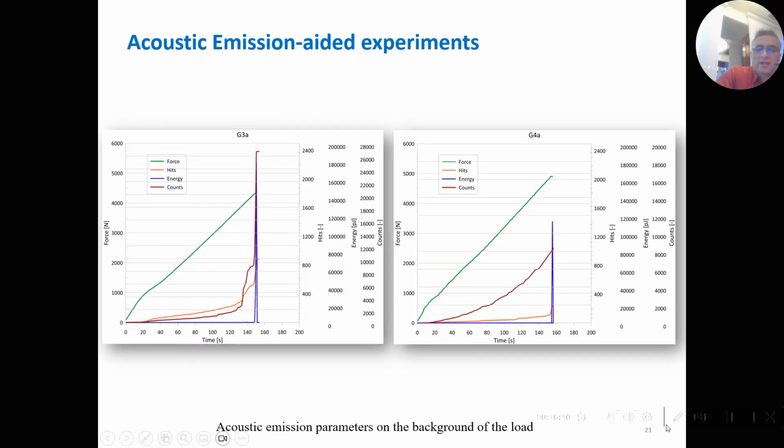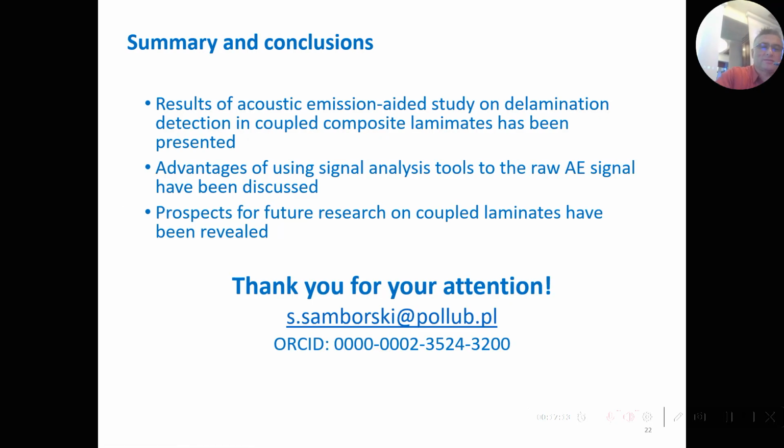There is also some data from Izabela Korzec, my PhD student, which shows for another type of composite that any of the measures of acoustic emission, either hits, energy, or counts, gives similar conclusions: when the loading process ends, for example, here you can see brittle fracture, every parameter of acoustic emission reaches its highest value.